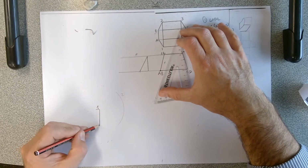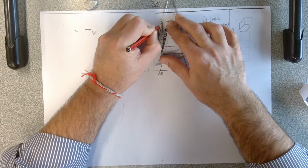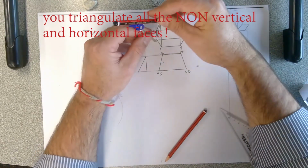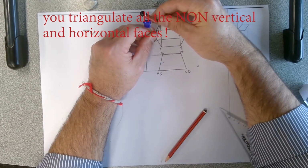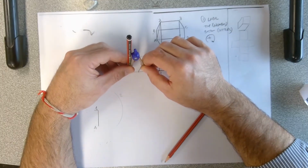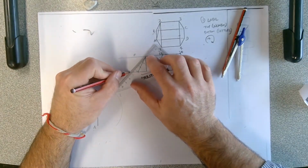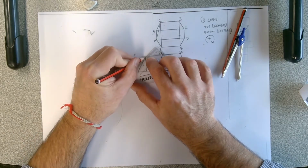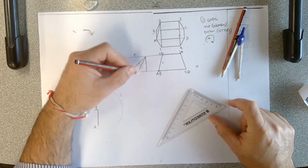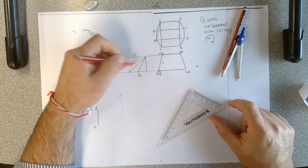I know that I've got my point A here, so I'm going to draw a line from A to 2 on this face. We triangulate all the faces in this process. So A to 2. So what I do then is I grab my compass and I put it between that line, A to 2, the triangulation, and I draw a line that goes like that. And then, you guessed it, I go like this. Now we said that this was A1. You want to make sure that you then label your line.